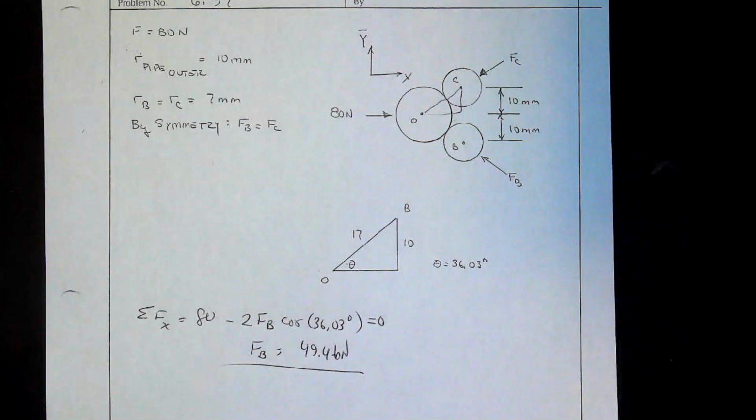So, knowing the moment, now I sum and got these. Well, now I know these. So knowing these, let's look at the situation. Do I care about C? Nope, not at all. So I'll sum the moments at C, and that'll give me this FD right away, and zip, bam, boom, problem's going to be knocked out. So we go right over here. We sum the moments at C, set that equal to 0. That's all fine. EY is lined up with C, so that means it does nothing.